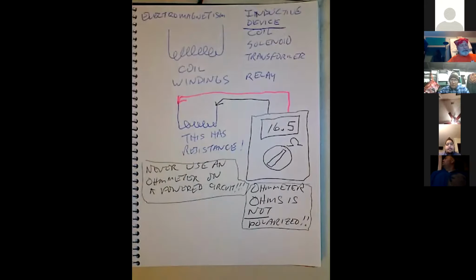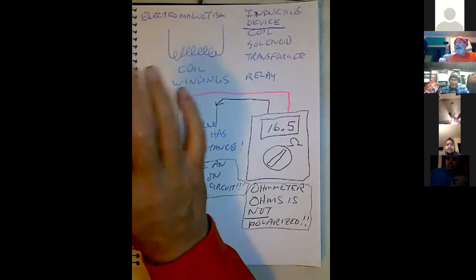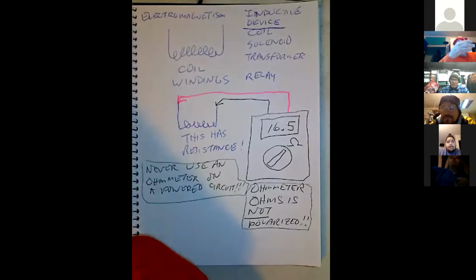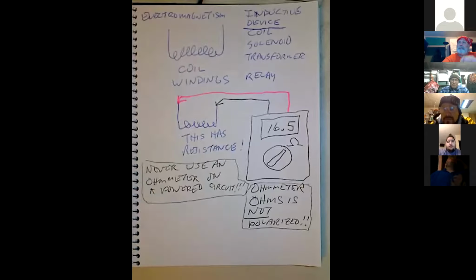Okay, Chuck, I'll do this for you. On a computer power supply, you've got 5 volts and you've got 12 volts, right? The 12 volts goes to all the motor circuits, like the disk drive, the hard disk, and the fan. 5 volts goes to all the information circuits. So 5 volts is the standard for all your information circuits, which is why on a car, your sensors are all going to be 5 volts, but your actuators are all going to be 12. I thought you'd like that. Makes sense though, doesn't it?